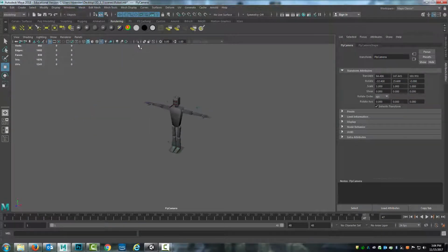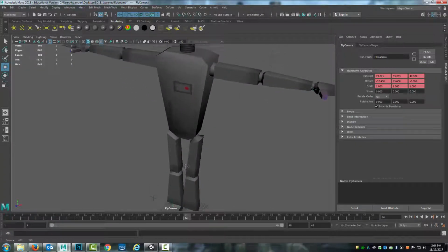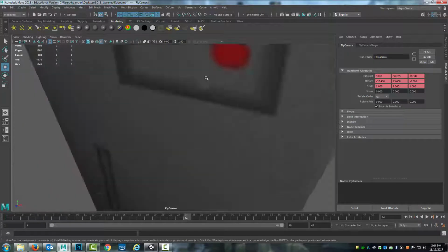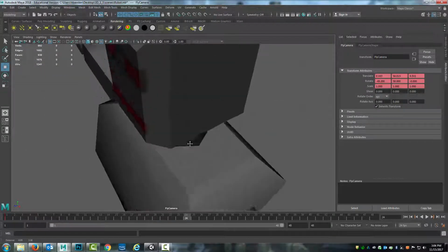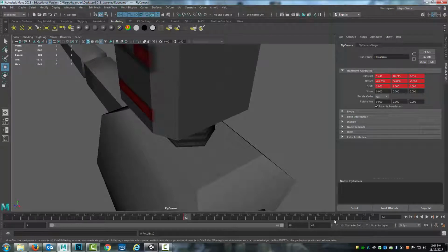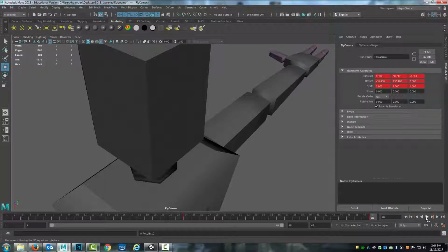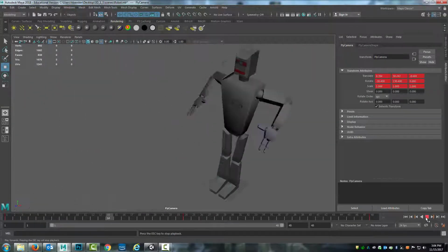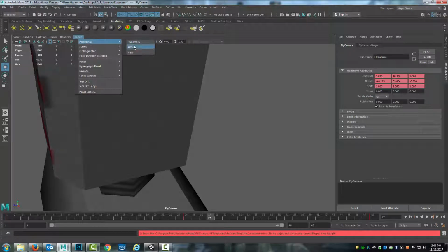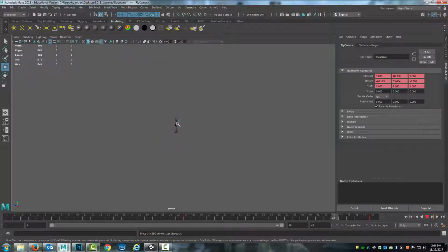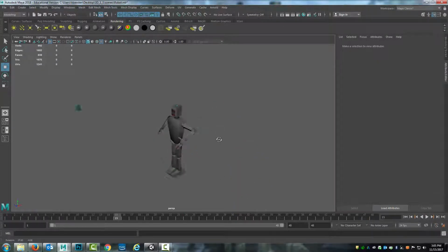So for this, I'll show you very quickly. I can do fly camera. At frame 1, hit S. Frame 24, I'm going to zoom in here, so that's right up here, S. Frame 48, it's going to come right around here to the back, S. And so now I can get this kind of like fly through with the camera. If I want to look at it from a different perspective, look at the perspective, and then just watch the motion of that camera. So you can see there's a lot of different ways to interact with these environments, with these worlds, based on the software that you're using, but they all kind of tie in together. So that's lights and camera.